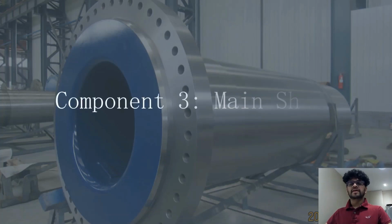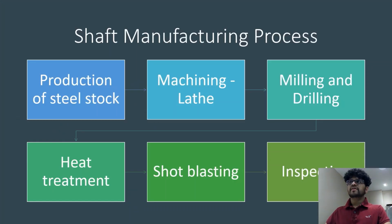Hi, I'm K.R. Patel. Let's talk about the third component of the wind turbine, the main shaft. The main shaft is the primary device that transfers torque from the rotor to the rest of the drivetrain. It also supports the weight of the rotors, and it's mainly made of steel. The manufacturing process for the main shaft involves 6 steps.